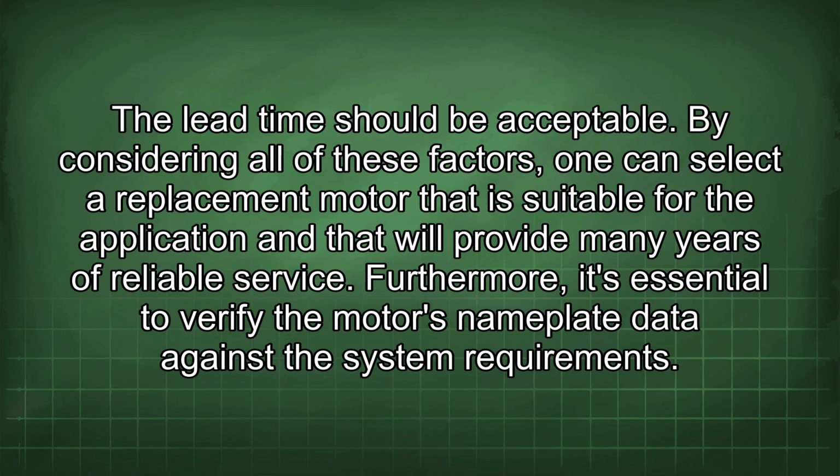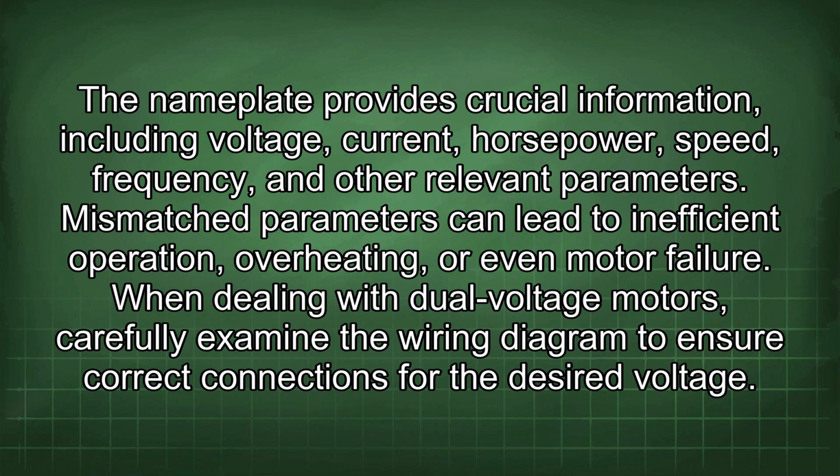Furthermore, it's essential to verify the motor's nameplate data against the system requirements. The nameplate provides crucial information, including voltage, current, horsepower, speed, frequency, and other relevant parameters. Mismatched parameters can lead to inefficient operation, overheating, or even motor failure.